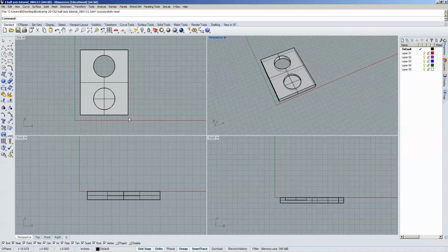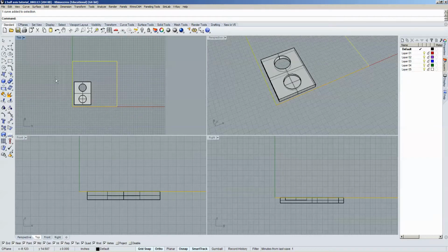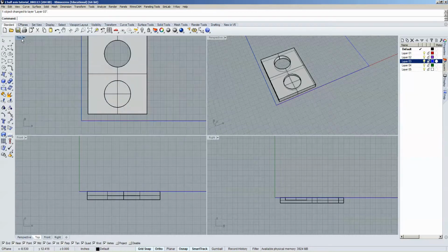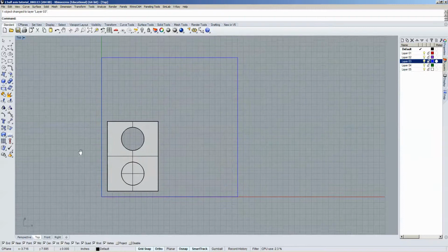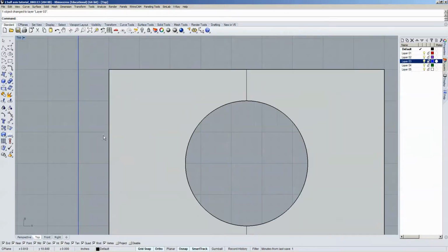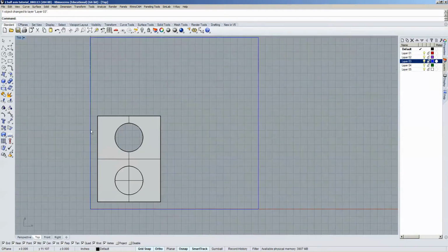I've offset it by 1 inch from our 0 point. I'm just going to draw a 24 by 24 square. And this is our material. I'm going to change the layer that's on so we know that that's the reference. So this gives us plenty of room to put a screw in the corner, and it also gives us plenty of room for the bit diameter to still leave material behind so the material doesn't get cut all the way free in the middle of the cut.